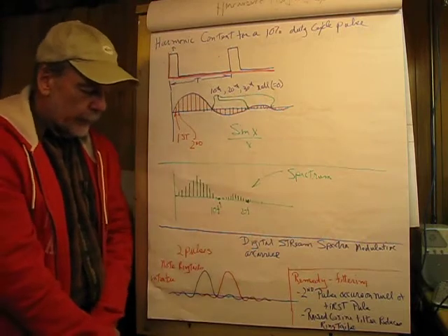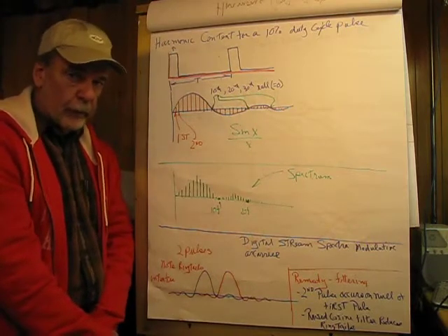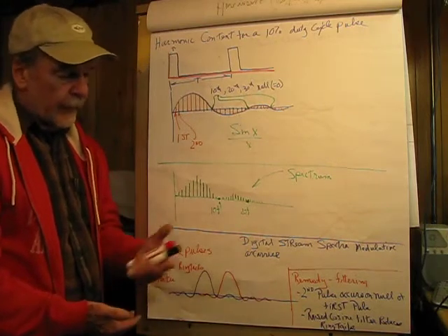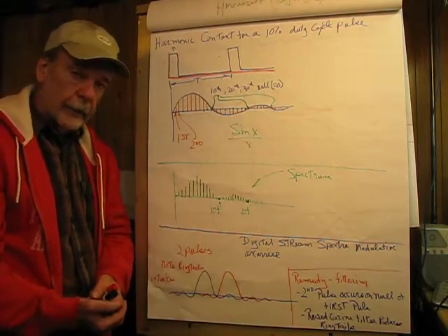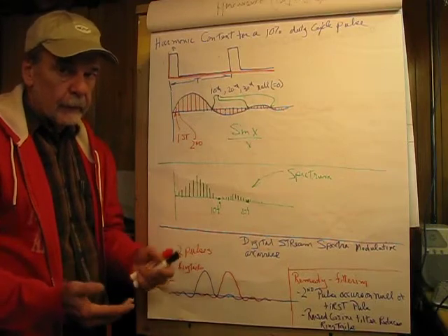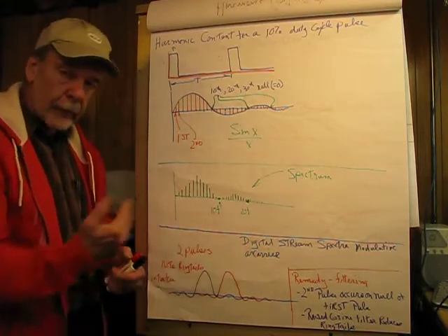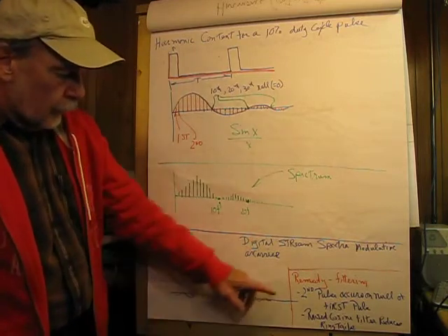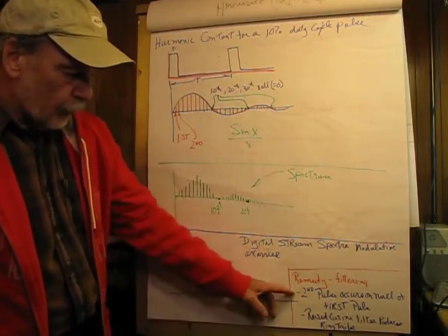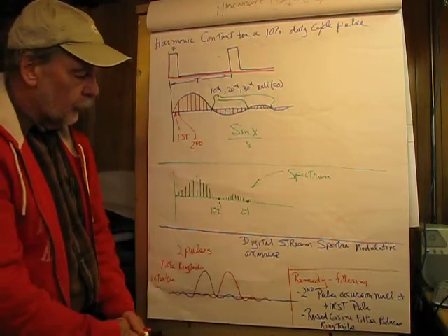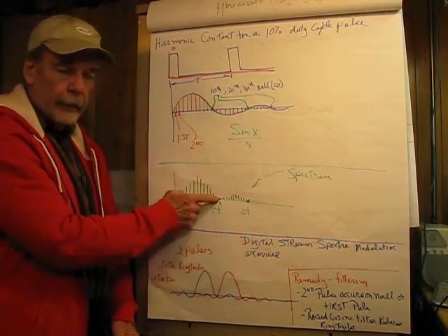Now, we can help fix this because we want to keep the error rate in a digital transmission system to 0. Because if you're downloading, say, a file on the internet, if you get an errored packet, you have to tell the sender that you got it in error, and he has to resend the packet. So the remedy on this is we can filter this, and if we adjust this right, the second pulse can occur at the null point.